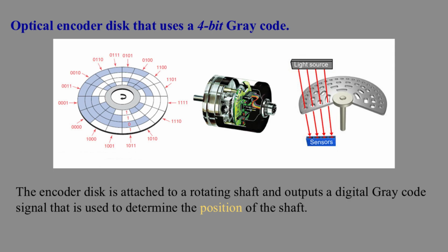In summary, Gray code is not designed for arithmetic, but for reliability in reading transitions. It is widely used in industrial systems to ensure accurate position sensing and motion control. That's why you'll often find Gray code in optical encoders, robotics, CNC machine tools, and servo systems. Its ability to minimize errors makes it an essential code for real-world automation and control.